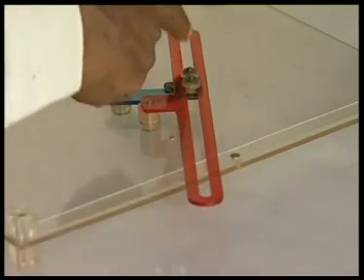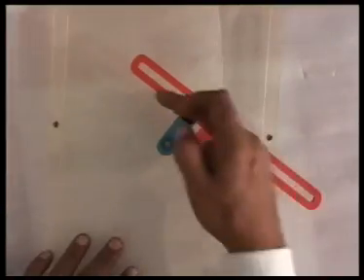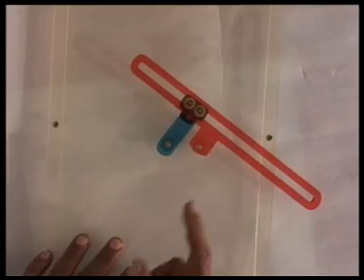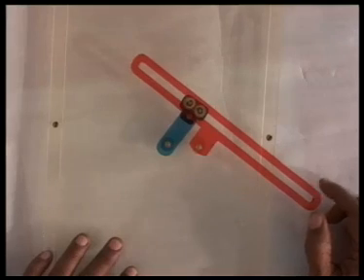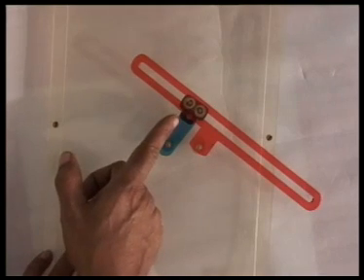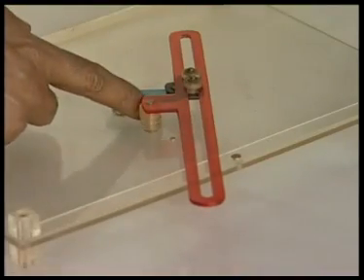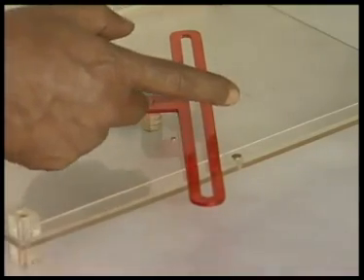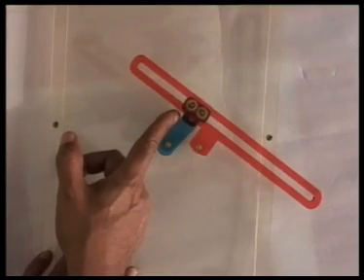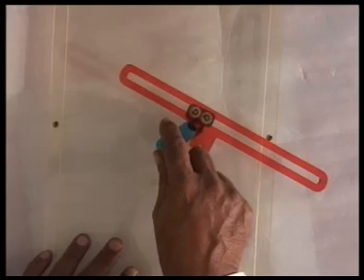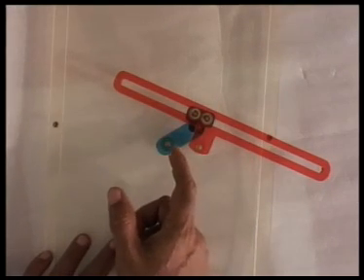This is that common tangent that I was trying to draw between those two circles. This line is parallel to that common tangent, and consequently this has reached its extreme position. It cannot be further inclined. However, this link can still go, and as you see from this extreme position, it is returning, that is, it is rotating counterclockwise, though this link is still going clockwise. And this is the extreme position of this link, and now it cannot go any further, it has to return.